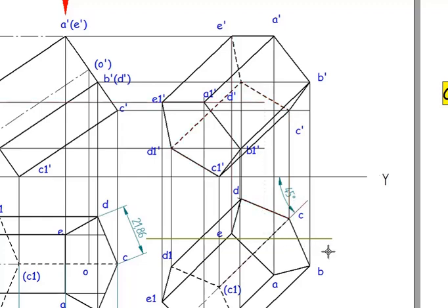Now the second farthest point is C, above this axis point O. So from the C point it should be hidden. C is joining to B, which comes under the outer boundary, no change. C to C1 is again the outer boundary, I am not going to change. C to D is already made a hidden line. So there is nothing left with C.